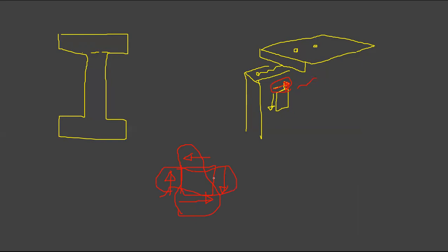Their shear capacity parallel to the grain, so in this direction, is pretty low. That's why it reaches failure first, right? Otherwise, this stress is the same, right? This is perpendicular to the grain. So this is the shear in this way.